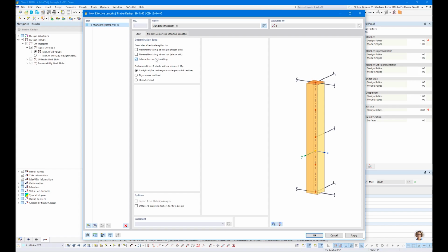We have three options to check it, because for lateral torsional buckling we need to know the critical moment or the critical stress. Based on this critical stress, we can check the equivalent member method. Let's start with the analytical equation to determine the critical bending moment or critical stress. This comes from Eurocode chapter 6.3.3.